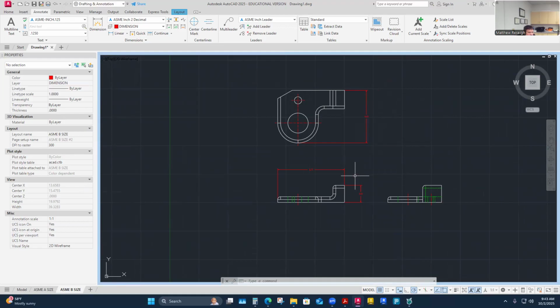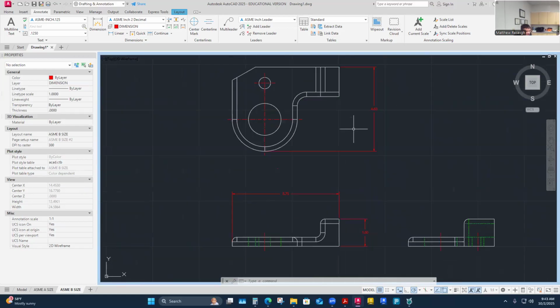And this is kind of all one continuous piece. So you've seen how I've usually proceeded to do dimensioning is I kind of look at the parts as maybe even separate, especially if they look separate, like a cylinder part next to a thinner plate part. Well, this one is definitely the most uniform part we've been working on so far, I think. But it does have some features still. We've got the overalls, but it has this little foot. I think of a feature of this thing as kind of the foot of this.